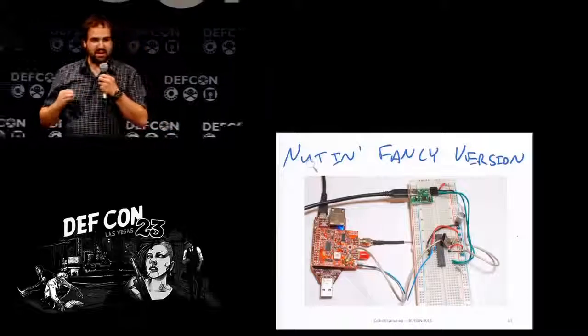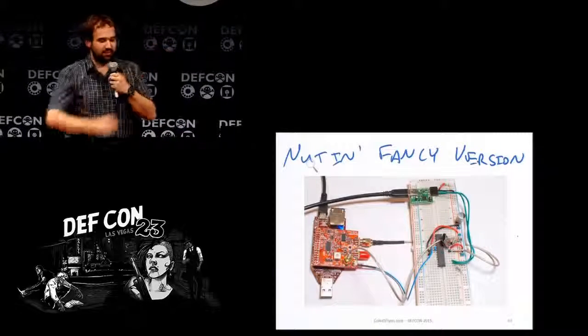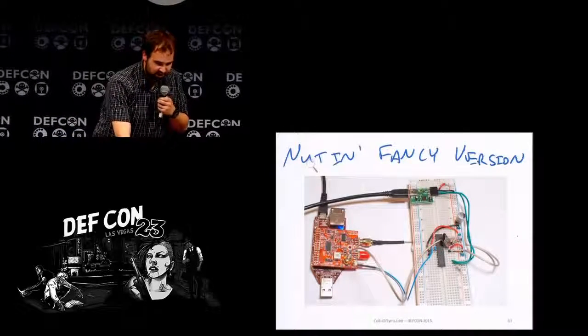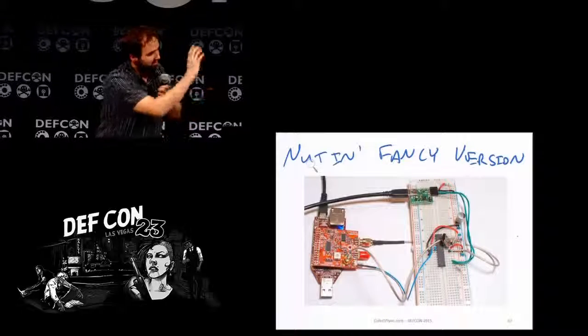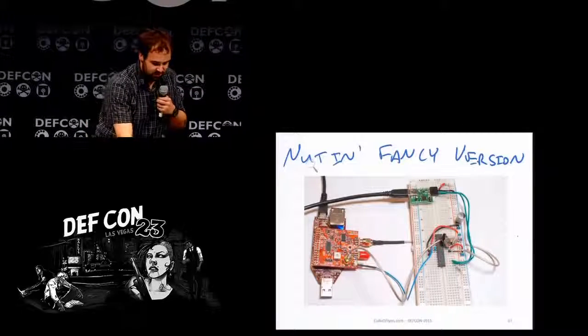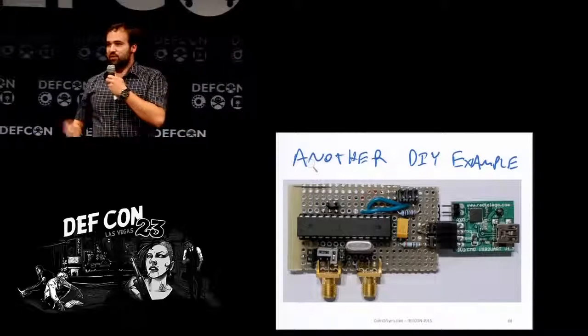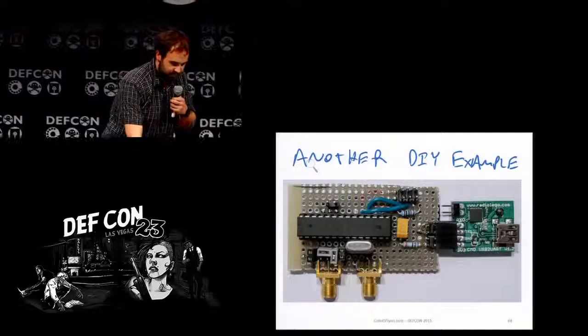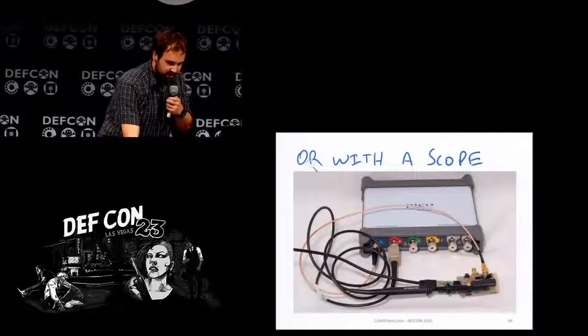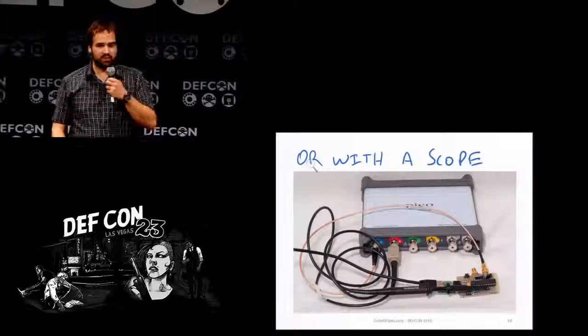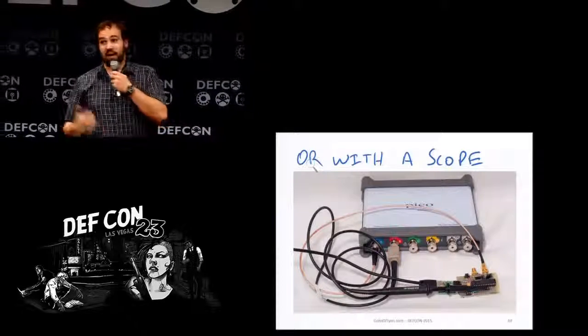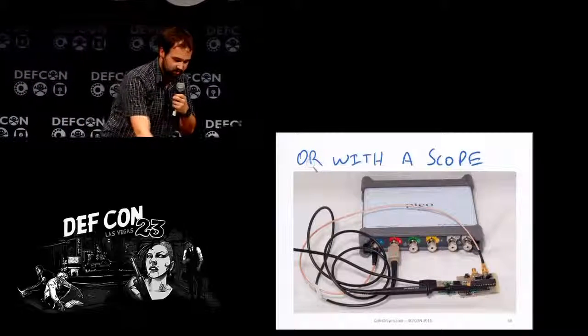This software doesn't only work with one variant of the hardware. I've built my own using some other FPGA boards before, and that's documented. You can build your own target device. So this is an Atmel AVR target you can play around with, and connect it to a scope. There are built-in drivers for PicoScope. You can add other scopes. Any connected device will work just fine.